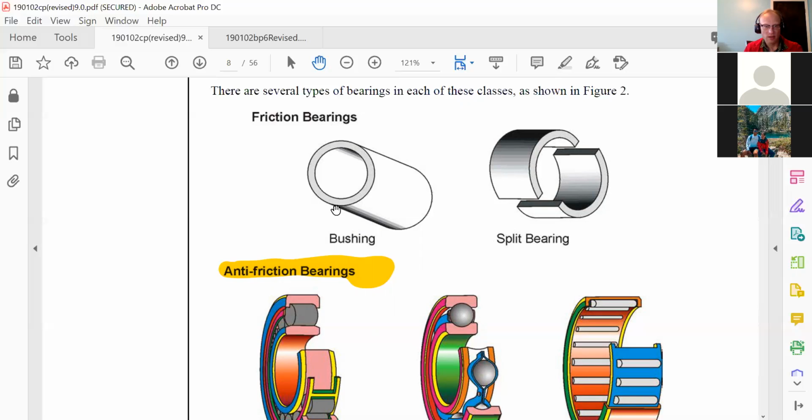Spring pins, S-cams, where else do you have them? Steering axle kingpins have friction bushings like this. There's all kinds of places where you'll see things like this. They can be made of different types of bronze, sintered brass, plastic, or nylon. Those are all friction bearings. We often just call them a bushing though.